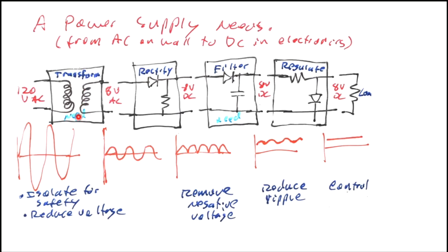We'd go from a transformer normally in any power supply, and the first thing we usually do is rectify it. So we have a big AC signal, and then we have a smaller amplitude AC signal. Then we rectify it, and we get just the positive going pulses. We might get every other one as a half-wave rectifier we already looked at, but there's ways to get all the pulses. So we get it rectified, so it's all positive voltage.